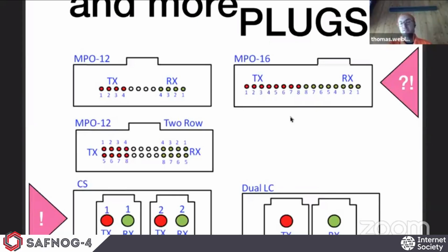But when we look at multimode transmission, doing 8 lanes with SR8 definition, it's going to be MPO16. So 16 fibers in one plug, and Y16 for sure. We have 8 lanes, and 8 times TX, 8 times RX combined gives 16 lanes. The good news is the MPO16 will have a new keying, so you can't mix it up with the MPO12, and they won't fit each other.